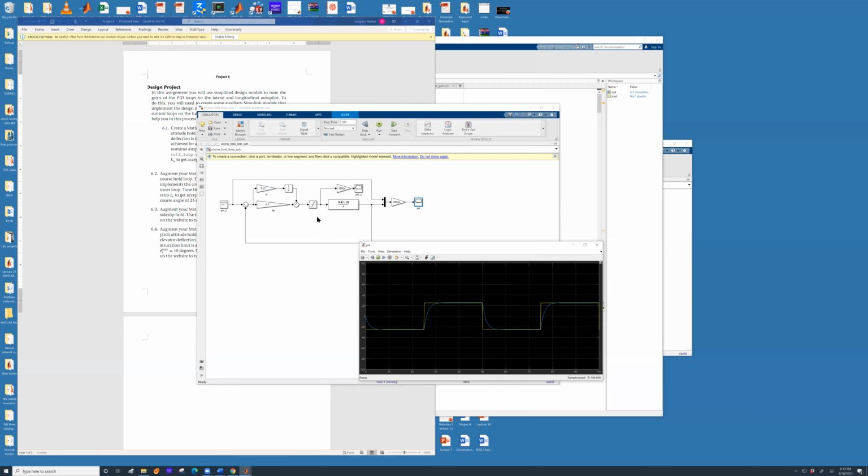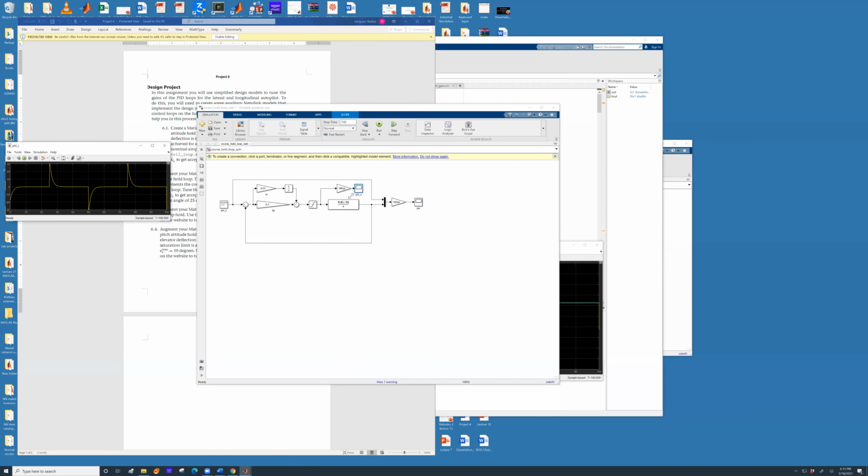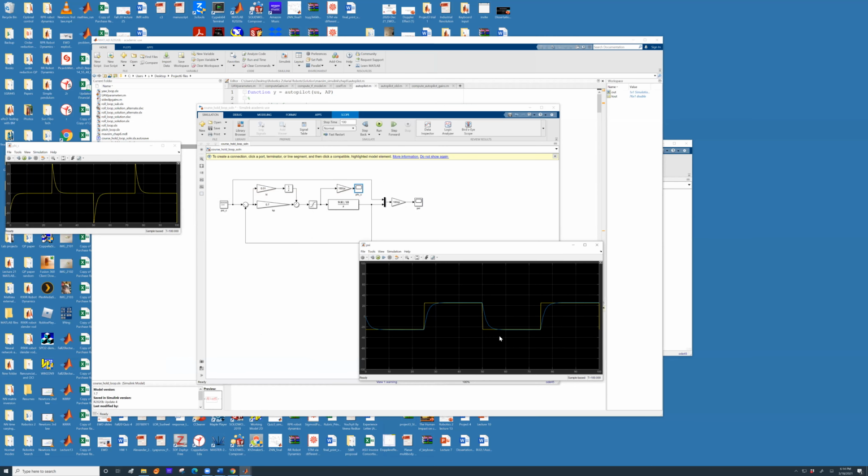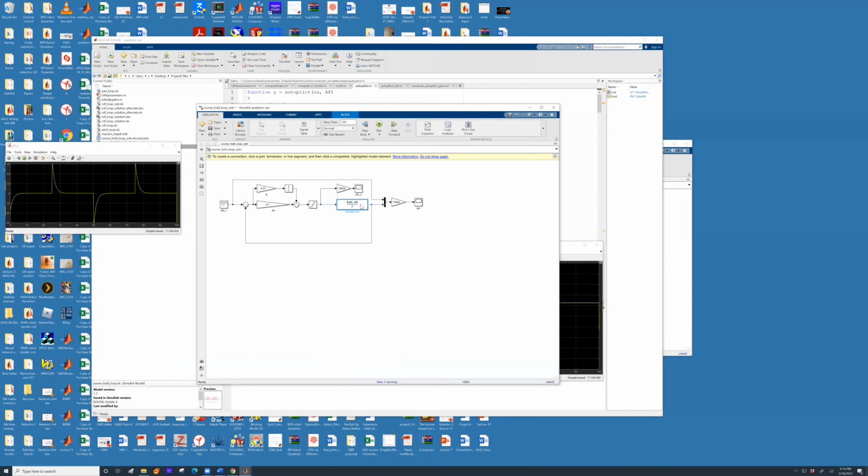However, one thing that is obvious, and you can look at the actuator gains, you will notice the actuator does not go to 45 degrees. Actuators are going to plus 30 and minus 30 degrees. So what this tells me is I have an acceptable performance with these gains. Now what I need to do is implement the roll loop inside this loop. So for that, here is what I'm going to do. I'm going to extend this a little bit.